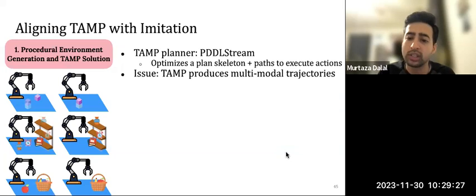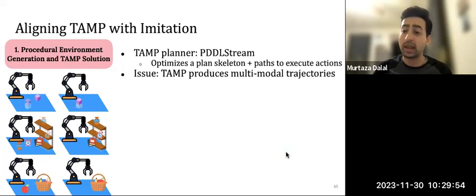And so what this results in is highly multimodal trajectory distributions, which for the same exact pose, environment, scene configuration, everything, will actually have wildly different behavior. And this is very challenging for imitation learning systems to fit to, because most likely what we'll end up doing is fitting to some sort of average. We'll address on the learning side how to handle multimodality, but we can actually take some steps on the data side itself to reduce the multimodality and make it easier for the imitation learning system to fit to the data.